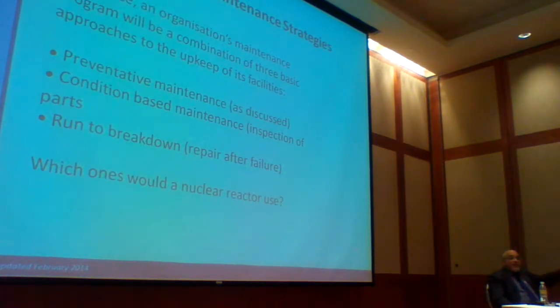Alternatively, if it is mechanical equipment, then you will be checking the vibration, the temperature, and other things which are indicative, like warning signals of a possible breakdown. So again, you can have preventive or detective maintenance rather than breakdown. And you have run to breakdown. Some of the machinery, we say it costs us too much to maintain or service, so let them run until they break down.